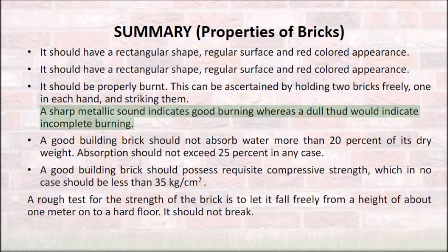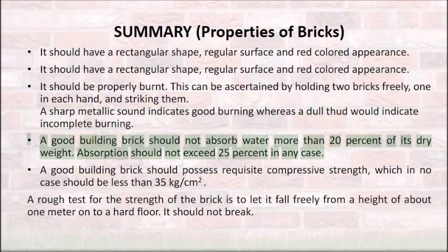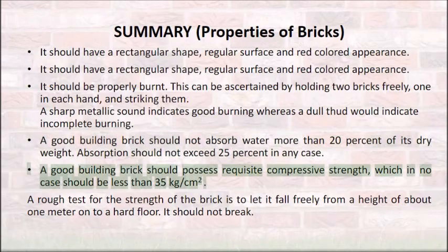A sharp metallic sound indicates good burning, whereas a dull thud would indicate incomplete burning. A good building brick should not absorb water more than 20% of its dry weight. Absorption should not exceed 25% in any case. A good building brick should possess requisite compressive strength, which in no case should be less than 35 kg/cm².